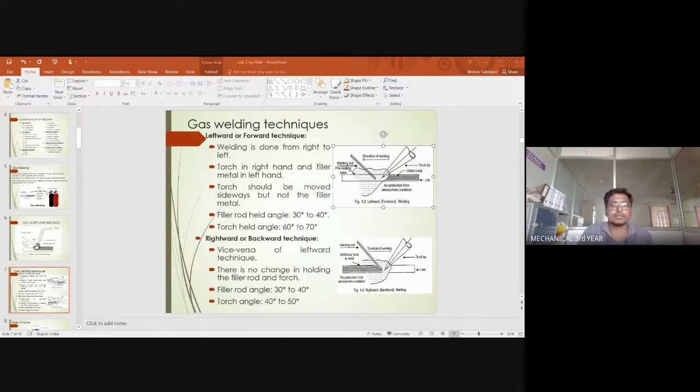Whereas in the previous topics, wherever you saw us talking about filler metal, there we were using a consumable electrode. Whereas TIG welding is the first type of welding where we are using a non-consumable electrode, which means that the electrode will not get melted. Here also, the electrode is responsible for producing heat, and due to the interaction of that heat with the other metal, the other metal will get melted.